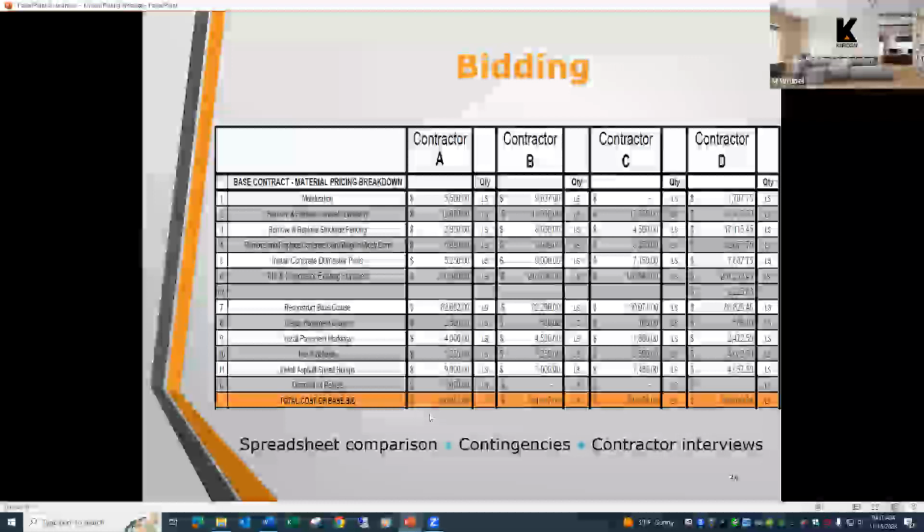Usually what we'll do is when we provide this summary, we'll show the cost of the base bid based on the contractor pricing, and then we'll include also a line under that shows contingencies between 10 and 20%. And those contingencies take into account those unit costs, those unforeseen items. So even though you have this base bid, just for budgeting purposes, we usually like to show a range between 10 and 20% contingencies. We find that just based on historical data from our other projects, contingencies average around 15% of the base bid.